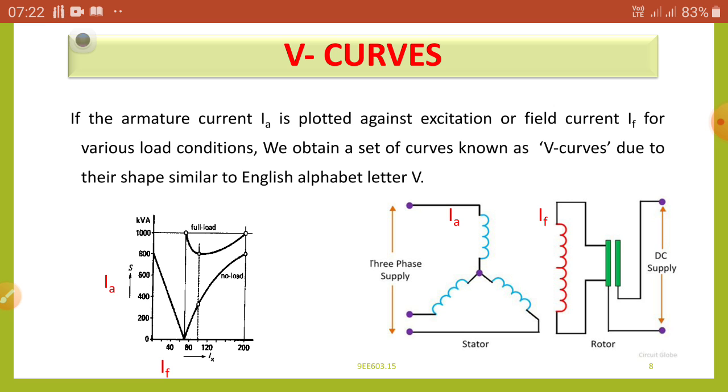After starting, we excite it and the stator and rotor interlock with each other. The motor runs at synchronous speed, then decouple the input prime mover, that is the pony motor. Then our motor is running as a synchronous motor.